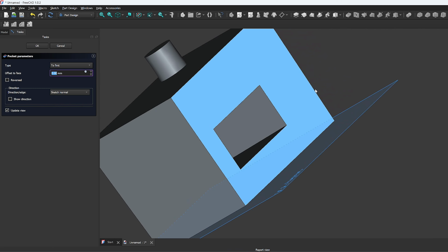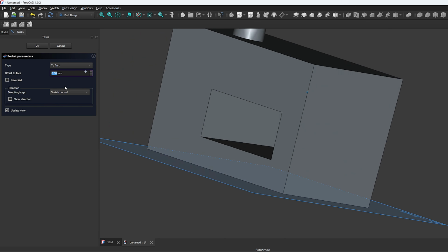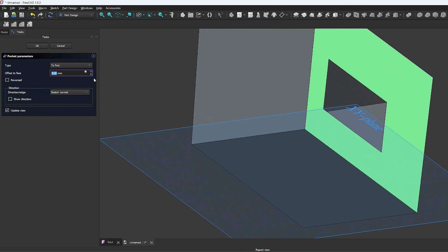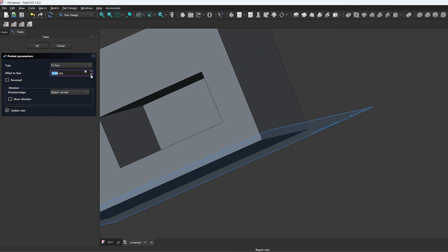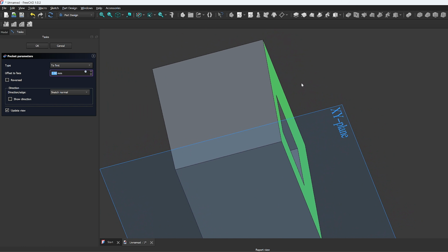In this case, this is the first face, so again you're going to see the through all style pocket. Here you can also customize it by changing the value. If I go minus, you can see it is again reducing the value of the cutout. If you go plus, let's say there is another entity toward this side, then the material would be subtracted on that particular entity.